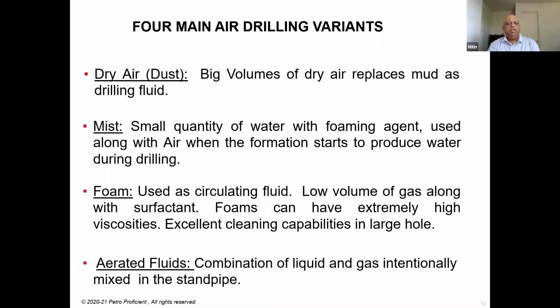So when we talk about lightweight fluids, there are 4 main variants in this. The 4 main variants are air drilling, which is also called dust drilling, then you have mist drilling, then you have foam drilling, and then you have aerated fluid. Let's examine all this one by one.